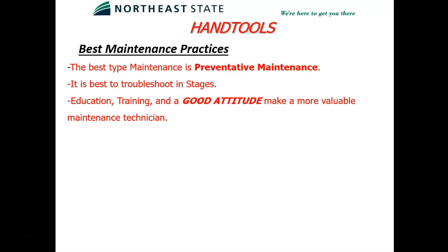There's another type of maintenance called predictive maintenance, and it's not practical in most applications, but you talk about oil, you can send oil samples off to have it tested to see how much viscosity is left in your oil. So, for car maintenance, it's not worth that. But when you get into industrial machinery where you have thousands of gallons of really high dollar expensive oil, it's worth it to have a program that has predictive maintenance. But, you know, the best overall type of maintenance is preventative maintenance. And you set it up on a frequency that's recommended or studied.